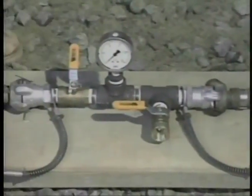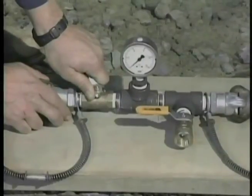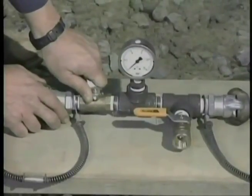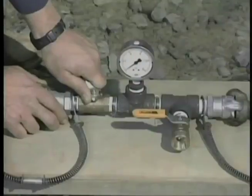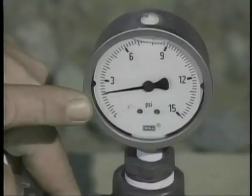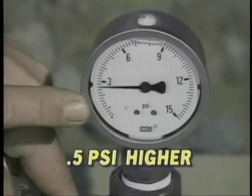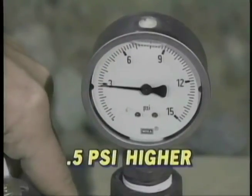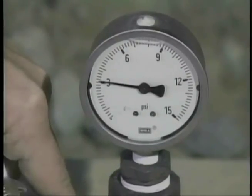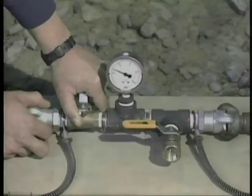Slowly open the air control valve and regulate the air flow to gradually increase the pressure inside the line. A sudden increase in the air pressure can blow the pipe or plugs apart. A common practice is to pressurize the line 1/2 pound per square inch higher than what the testing specifications require. This allows the pressure in the line and the gauge to stabilize.